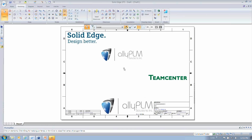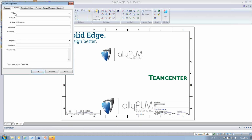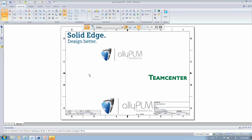Now let's take a look at how we can do customization in the draft environment. A lot of times our users ask us about property text in the draft. They tell us that they need to modify property text from 5 or 6 different locations through the property fields. We've got the summary where we use the title. We've got the project information, which is our part number, our current rev level, and the name. And then within our custom folder, we put all kinds of company standards of what we'd like to see. And it really takes quite a bit of time to fill out this information.